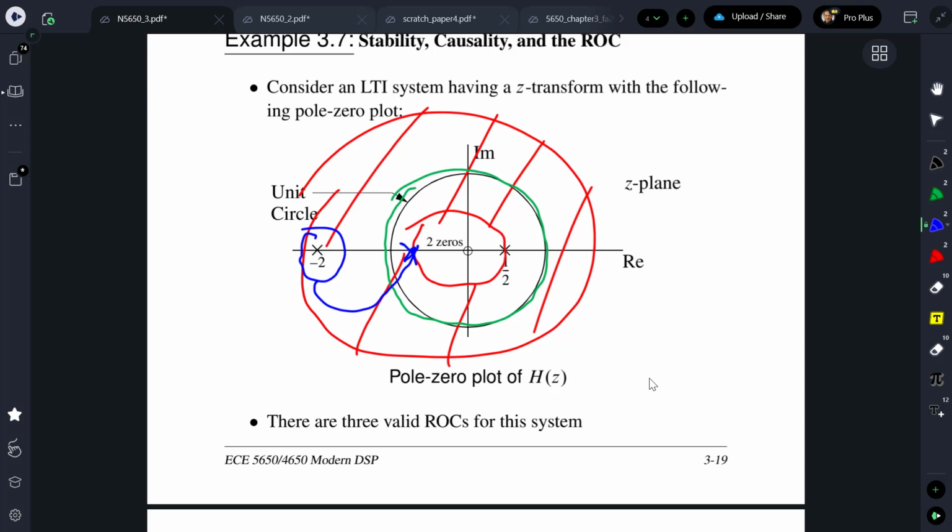What will happen has to do with the arrival of wavefronts at us, like in a radio communications channel. When we have multipath, we're getting a direct path, which is going to be the shortest path, and then we might be getting another path that bounces off a wall, bounces off another wall, and comes to us eventually. Does that make sense, that we can have that ray trace? The ray that bounces off the wall is going to take longer to get to us than the one that's direct. Now, what makes this become non-causal for equalization purposes is if the direct path is weaker than the path that has to take multiple reflections. And that's possible mathematically speaking and in practice.